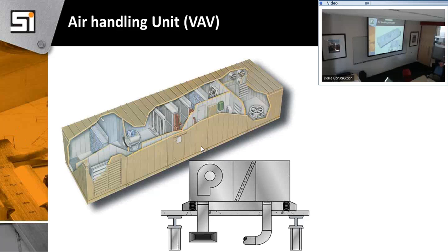Is that common for CO2? It's been mandatory for certain spaces, based on density, and I let my kids do most of the work anymore. I think it's 40 square feet per person, and above about 10 people is a space that requires CO2 sensing.